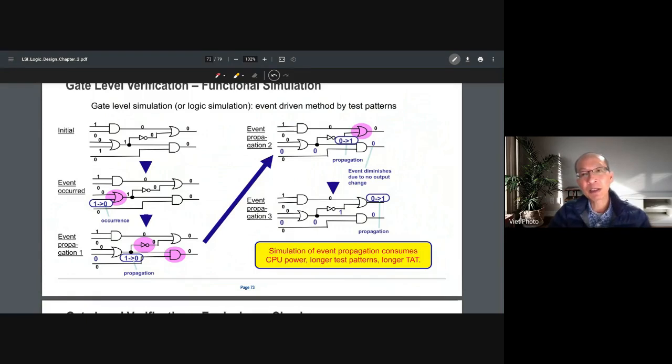So that's one you have in the lab to verify, right? When you verify, it means you apply the event, you apply the test vector and you measure the output to see if the output is as you expected. That's what the functional simulation is doing. So the simulation is always cumbersome, and to process that, usually you dump out, I think there's a text format for the output, and you have to write a script or a program to check it.